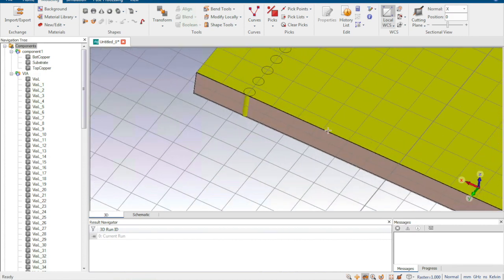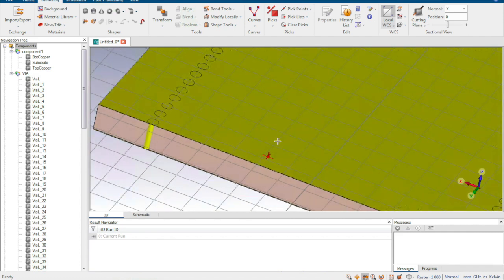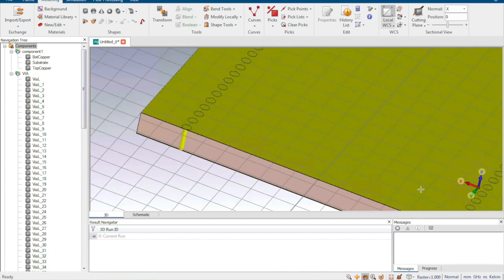So we can imagine that the EM wave in the substrate can propagate, but because there are metals at the top and bottom, left and right, these metals can limit the EM wave. So now we build up a SIW. This SIW works similar to the traditional rectangular waveguide.